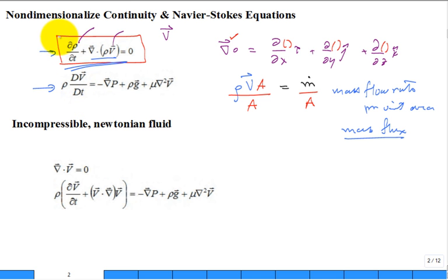All right, what about this equation? If that's the continuity equation, what do you think this equation is? The Navier-Stokes. I know we have some of the terms jumbled up, but this is a pressure, force per unit area. Gravity, what's that? Body force. And what is this term? Viscous. If you think of viscous, that'll be a surface force.